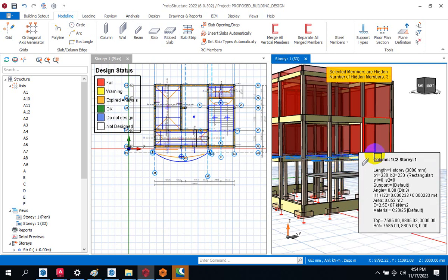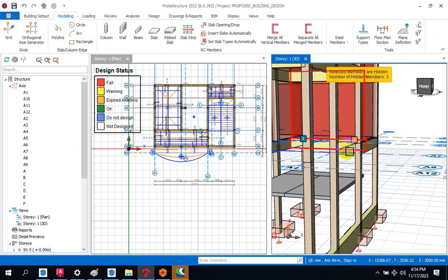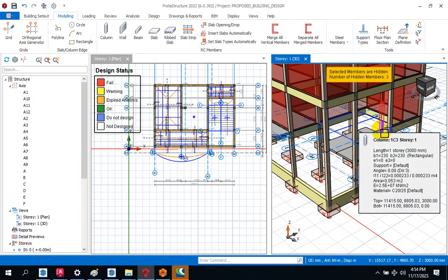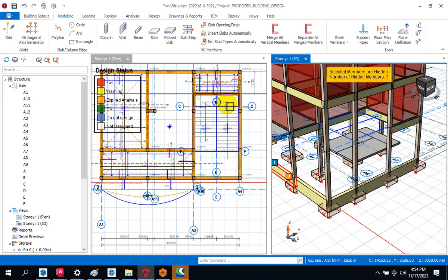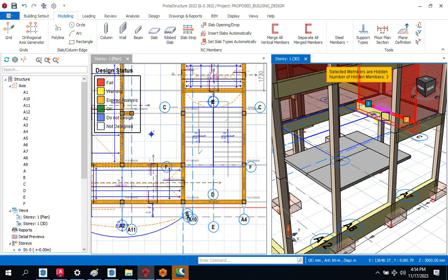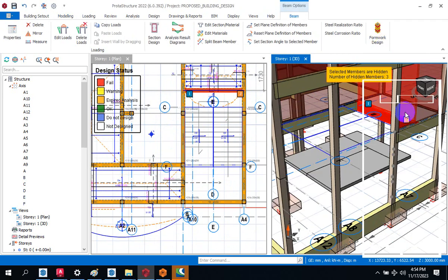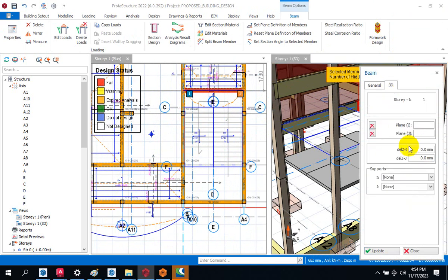No, this one that is suspended is not right. It's just for us to introduce another beam. I can take this beam down and introduce another beam. Similarly, you just select it, go to the property, and change the level.